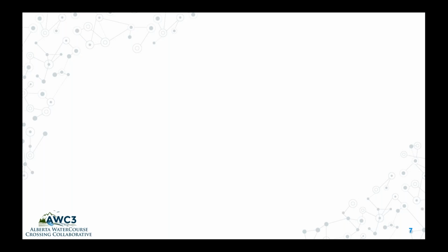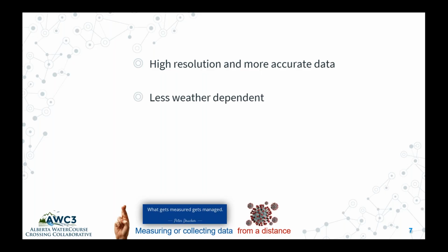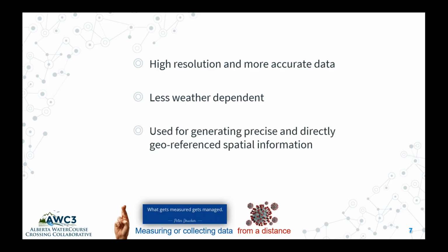Now, if you go back to our justification of measuring or collecting data from a distance, what LiDAR provides us is higher resolution and more accurate data. It is less weather dependent. You can even do it at night. It has the ability to generate precisely georeferenced spatial information about the target, and has the power of being a 3D documentation of the target that can later be accessed for computation of other parameters without personally revisiting the sites and objects.